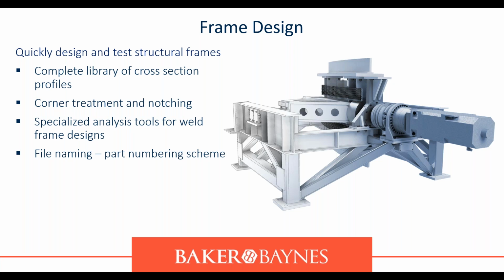Now, how this works, you will draw a frame with the line command. Then there is a frame generator where you select what type of steel, what type of frame you would want. And then as you click on the line that you drew, it inserts, let's say, angle iron on that line. And so you don't have to go create or extrude anything. You draw one line, go on the frame generator, and it creates it for you.